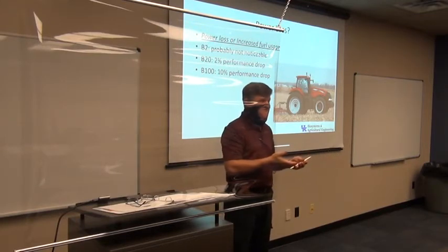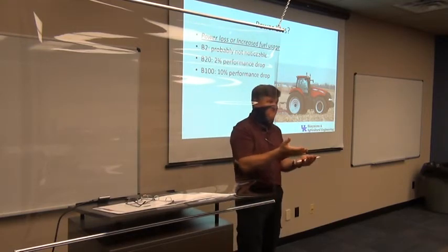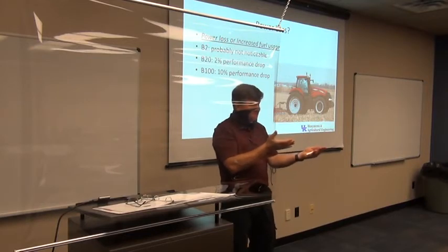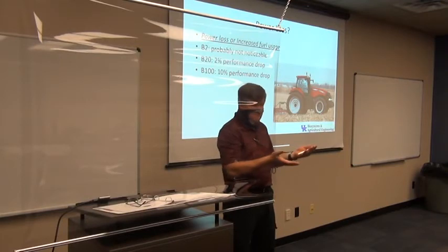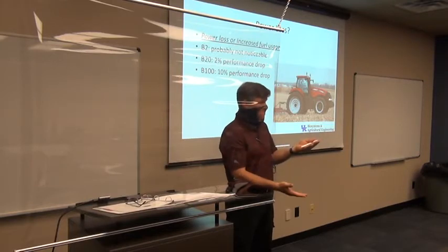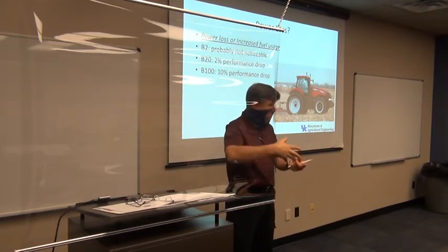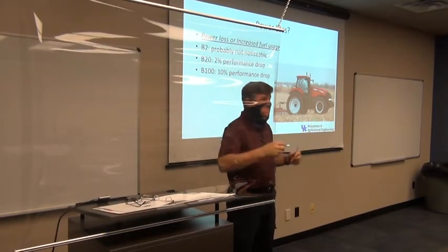Possibly. Okay, so there are really two different things that could happen. I could have a lower power because there's a lower energy density in there, but that engine might be handling that fuel differently. It might actually get worse because it's a thicker fuel. The flow rate might go down, plus the energy content going down, so it may have a much lower output. Or the engine, because of the way the governor works, might open up a little sooner and actually move a little bit more of that fuel through it. I'm not sure what's going to happen.